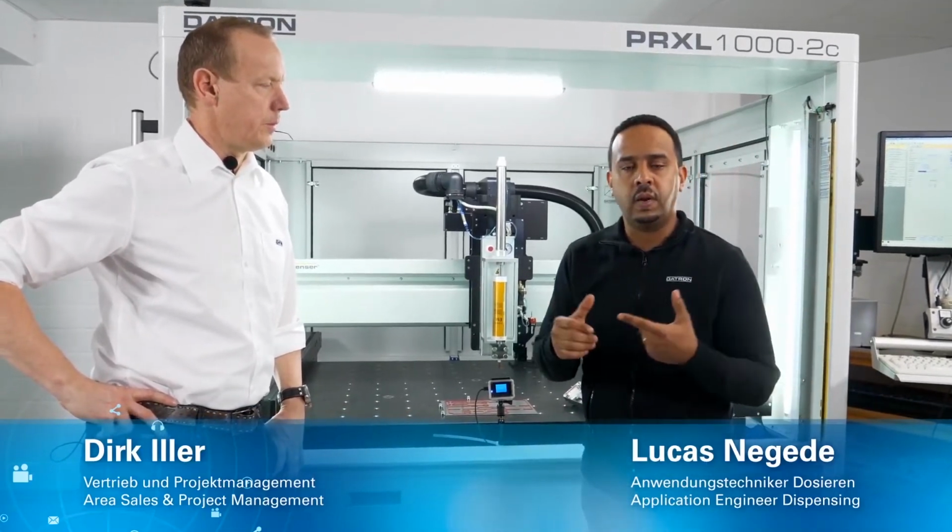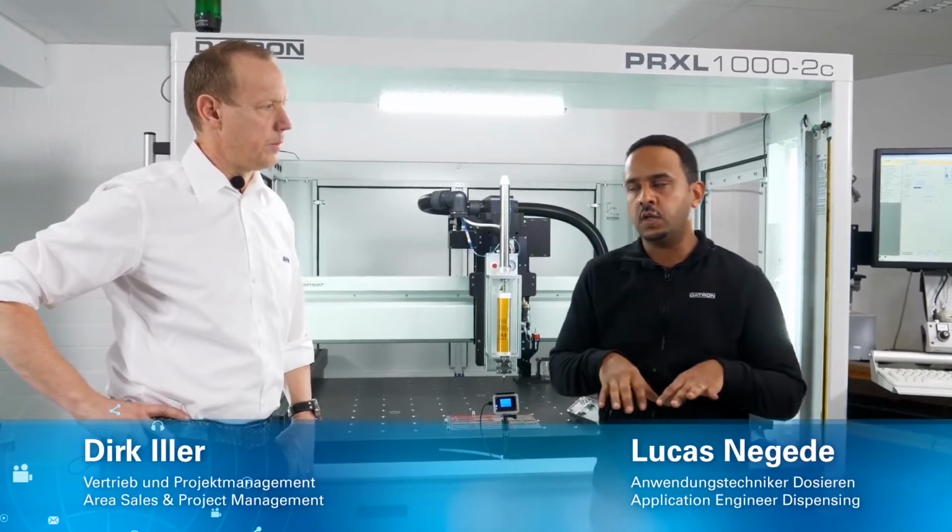Additionally, we can add a plasma head to clean the surface of plastic or aluminum parts. This is pre-dispensing, so that means a pre-position of dispensing. Before dispensing, we do the surface treatment. Afterwards, we dispense the material to have good adhesion between the material and the surface of the product.